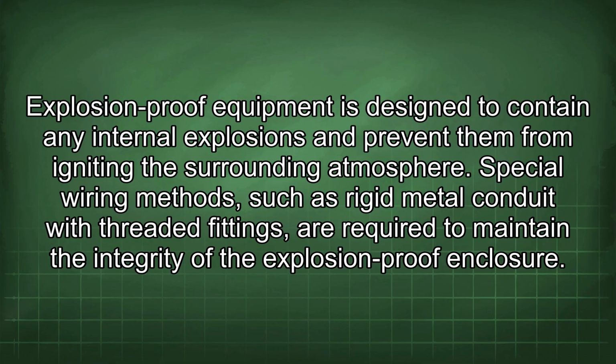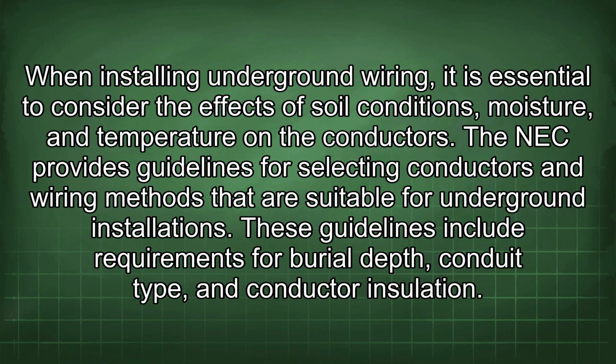When installing underground wiring, it is essential to consider the effects of soil conditions, moisture, and temperature on the conductors. The NEC provides guidelines for selecting conductors and wiring methods that are suitable for underground installations. These guidelines include requirements for burial depth, conduit type, and conductor insulation.